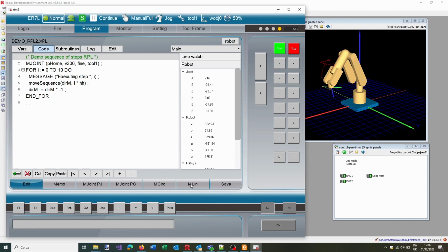In this way, if you just need to make some steps like a pick and place motion, it will be really fast to develop. You will just move, then set some parameter to close the tool, then move to the ending point, open your claw or your tool, and then move away, and you are ready to start again.